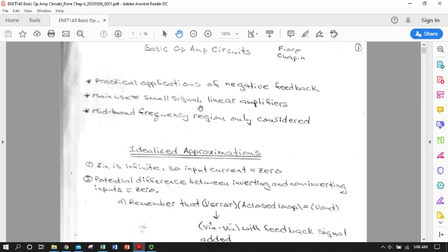Generally speaking, we would look to be maybe an order of magnitude away from the supply voltage limits and well below the output current limits of the op amp. Just like in our small signal BJT amplifiers back in the semiconductors course, we're probably in the millivolt region, 100 millivolts max, not volts, and a few milliamps of output, up to maybe 20 milliamps being the typical max output for a lot of general purpose op amps.